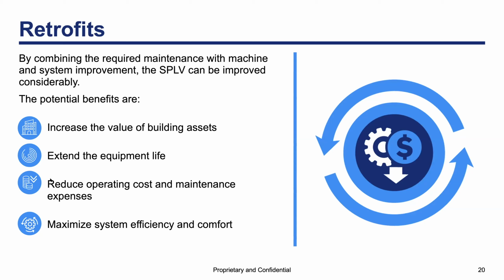As an example, which I've seen in many mechanical rooms, when a VFD is used to control the pump, I still see this triple duty valve installed in the piping. But think about this: there is no reason for the waste and cost of a triple duty valve, even if active VPF, or variable primary flow, is not being implemented. The speed of the pump can be adjusted to control the flow and have greater savings over the triple duty valve.